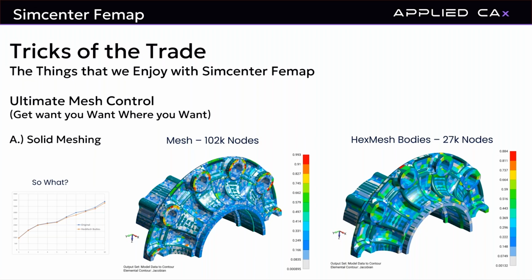Having a big model that's really slow, that you have to carry around all these results, I really try to avoid it, especially if you're doing PSD work. So I'm always trimming down the mesh. And one of the ways I check to see how far I can trim it is I'll run a normal modes analysis in the free state.